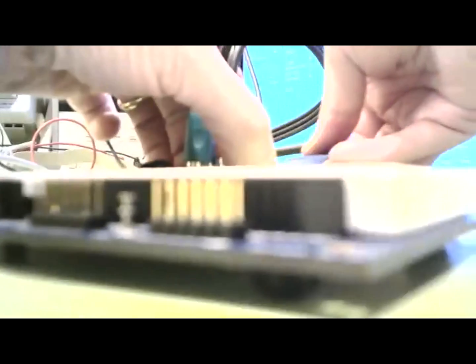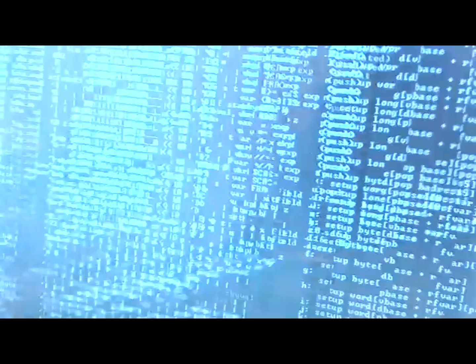Let me dim the screen a little bit by plugging in something in parallel, which will lower the voltages a little. If I can make it dim enough, you might be able to see it better. This is signaling pixels at 148 megahertz, 108.5. That's amazing. That's 6.7 nanoseconds per pixel. It looks great to me, but it looks horrible over this camera. Well, we need a zoom driver for the P2. Oh, yeah. There we go.